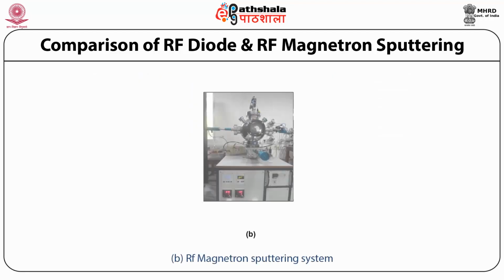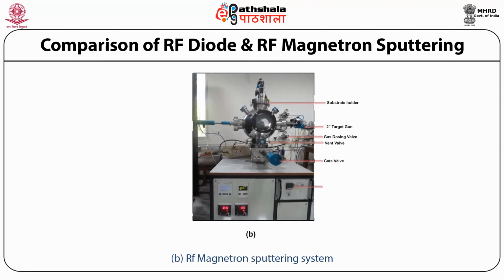The figure here shows the RF magnetron sputtering system in which we can see a substrate holder, the two 2-inch target guns, gas dosing valve, vent valve, gate valve, matching network. Then there is a turbo pump controller, pressure gauge display, the gas MFC controllers, that is argon and oxygen MFCs, and again the substrate temperature controller.